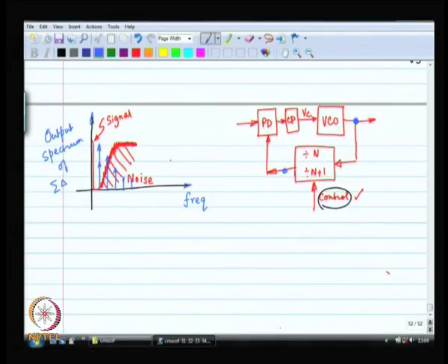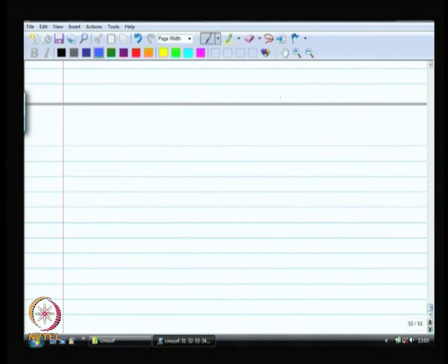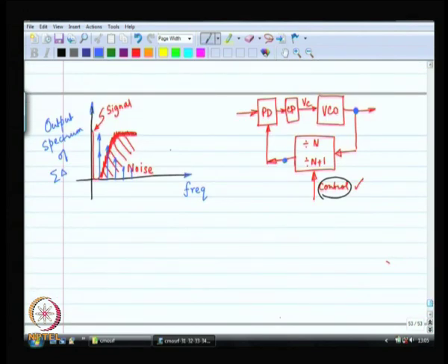So, given that the control signal output is no longer periodic, you can expect the signal over here to be not periodic at 1 megahertz anymore, but yet you are going to do some sort of a division by n plus a fraction, which means that you have done your job. Now, therefore, what do you expect at the output of the VCO?